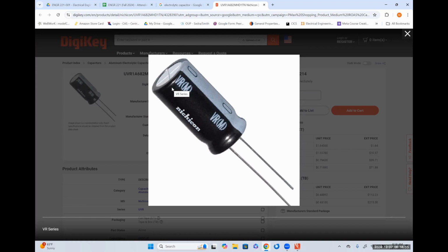If you open up the power supply unit for your computers and most modern electronics, you're going to see things that look like that all over them. The reason why electrolytic capacitors are used in a lot of power supplies for computers is because even though we could plug our computer into a wall so that it technically runs off of AC, there is a device in there called a rectifier that is converting that AC power into DC. So there should never be a negative polarity voltage across this because of the rectification of the AC signal.